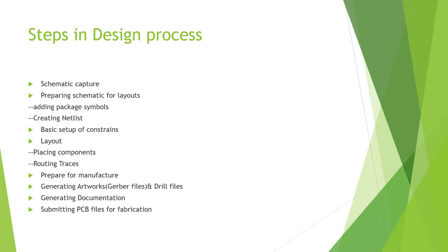The next step is to prepare for the manufacturer, who requires their own files. When you create the layout, it is created in a board file with the .brd extension. For sending to the manufacturer to create the PCB, Gerber files are required. A Gerber file is simply a layer file, a layer of our design, such as the top layer, bottom layer, inner layer, silk screen layer, solder mask layer, and many more layers we create in the layout.